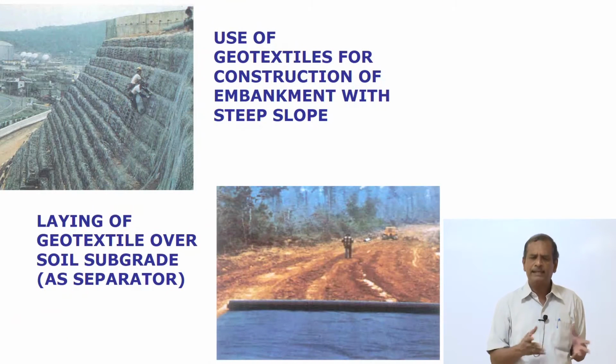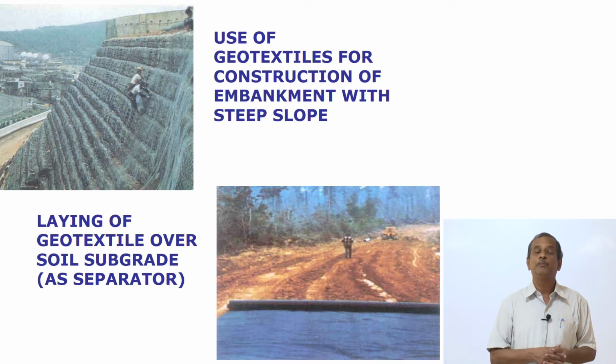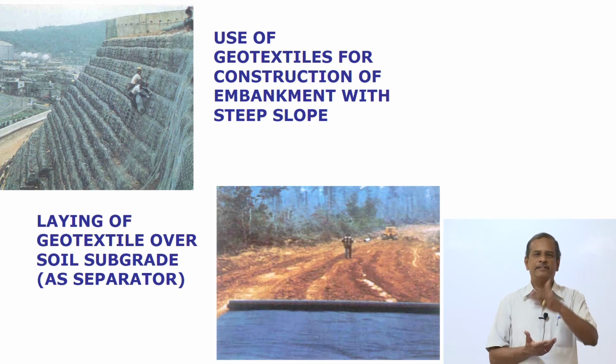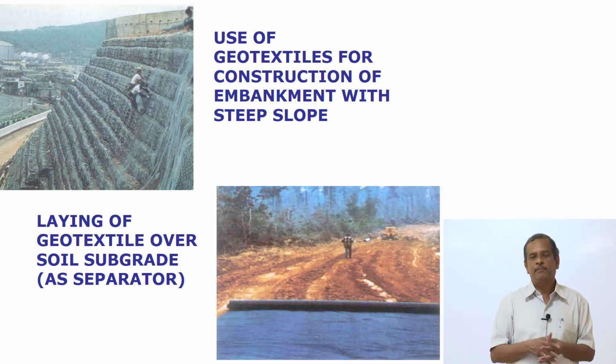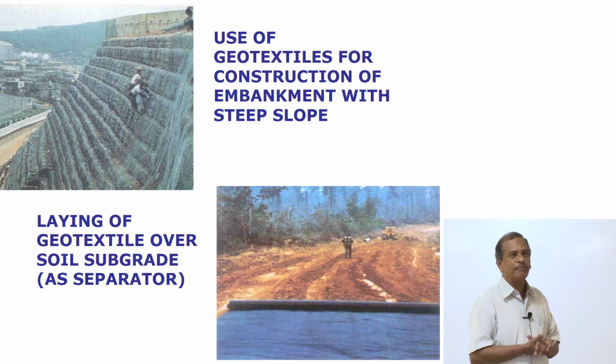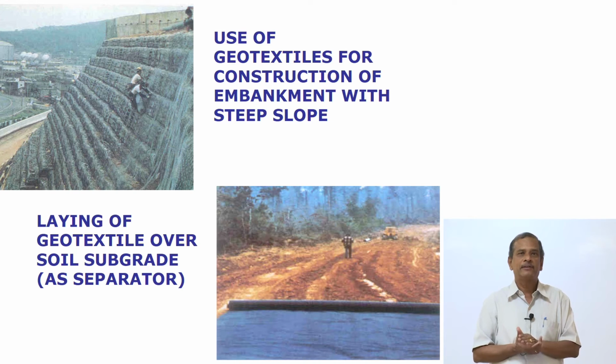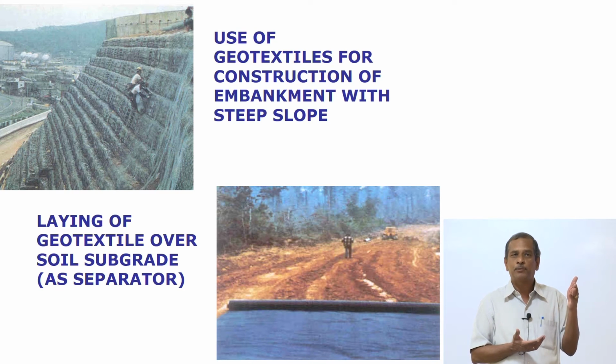Again, we have got better materials. I think it's time that we use new materials. One new material that can be used is geotextiles. I think after the recent floods last year, many of the roads in Kerala were cut off because of landslide. So what should I do now? These geotextiles can be used for embankment with steep slopes to ensure a better slope stability.